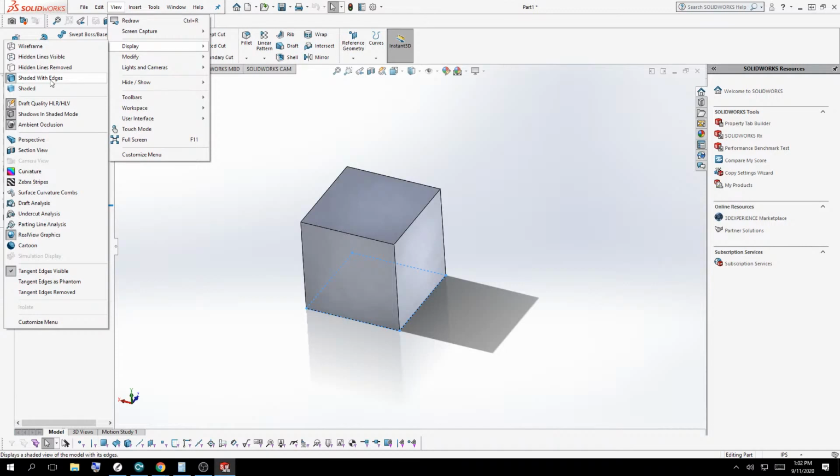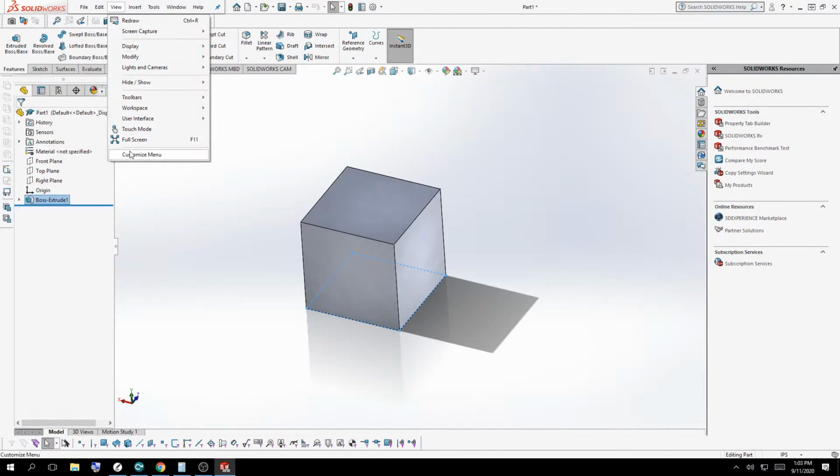That's first thing. And based on your video card in this classroom, I know that we have video cards that can enable this. We want to go down to Real View Graphics. We want to make sure perspective is not on. And then when you do so, you should be able to see shadows, reflectivity, edges that obviously will use shading as well. So you'll get a little bit more of a realistic view. If perspective is on, things are going to look a little bit distorted. And once again, that's a concept that we'll focus on another day.